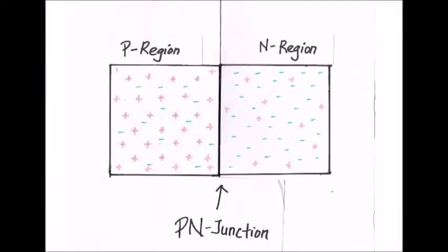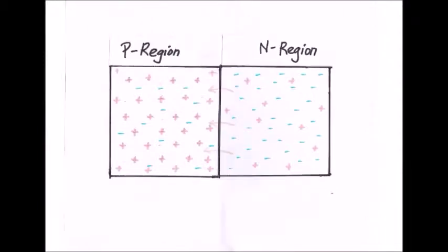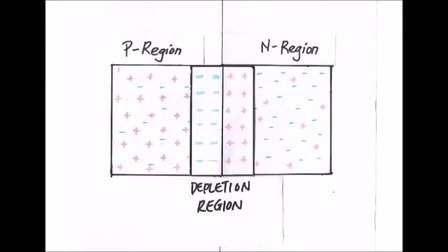When a p-n junction is formed, diffusion occurs. Electrons from the n region give up energy and drop into a hole near the junction, leaving a hole behind, which forms a layer of positive charge. While holes in the p region are filled by electrons from the n region, it creates a layer of negative charge. These layers form a depletion region.